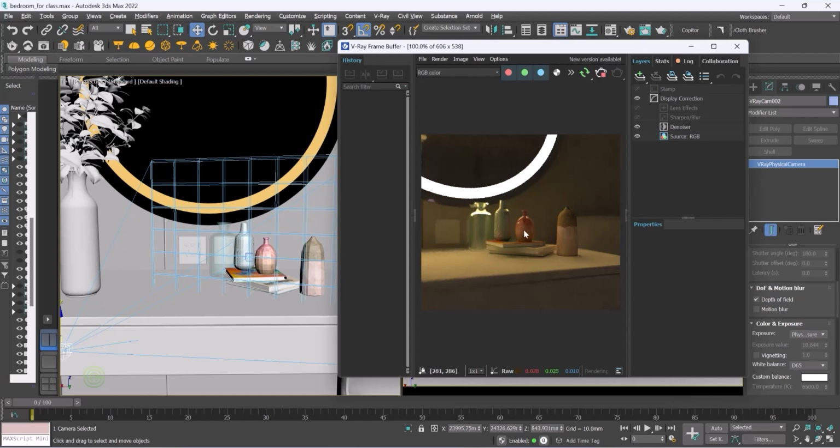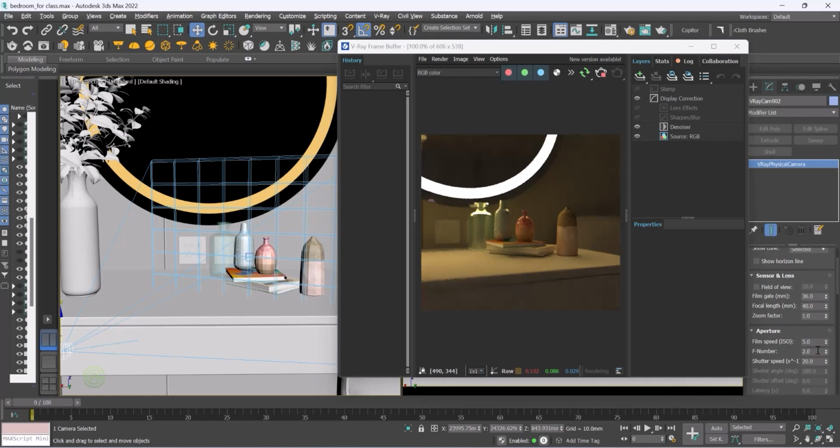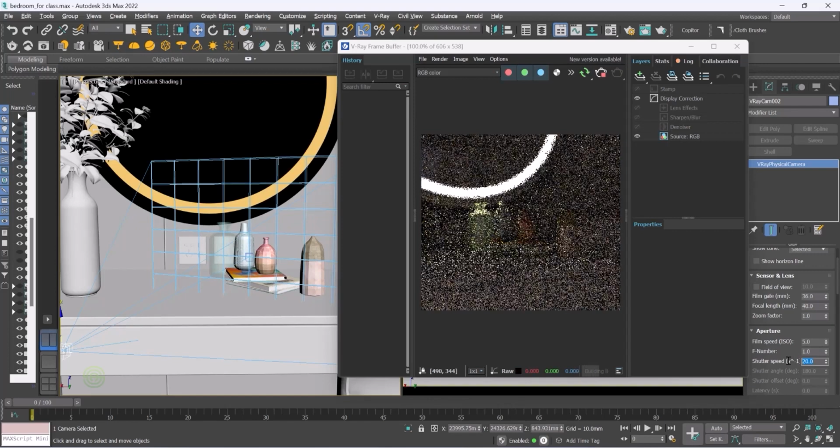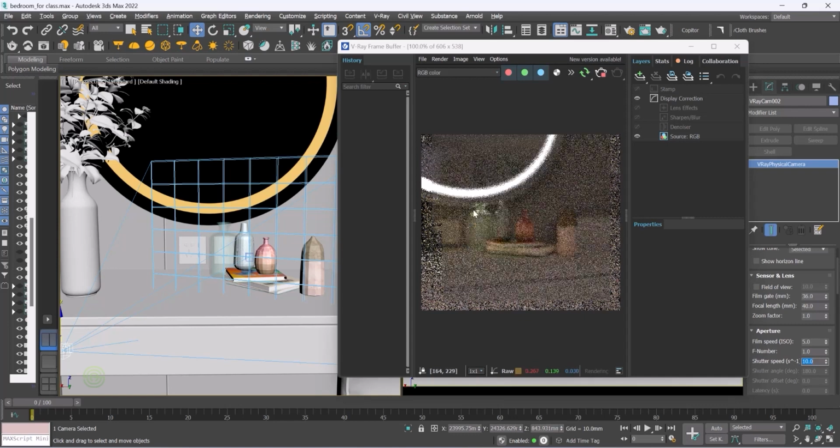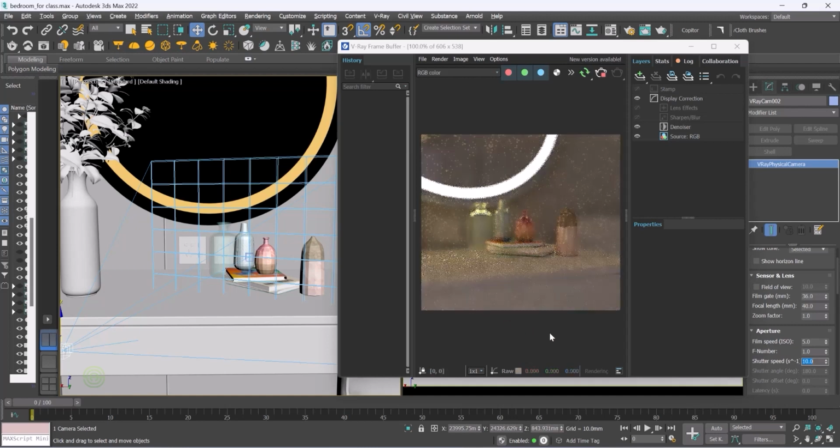And we can also adjust the aperture. So we can just change the f number to 1 and then shutter speed as 10. So the surrounding will be more blurred than the previous one. So just see this render. Comparing to the previous one, in this render, the surroundings will be much more blurred. So let's wait for a few seconds till the render happens.